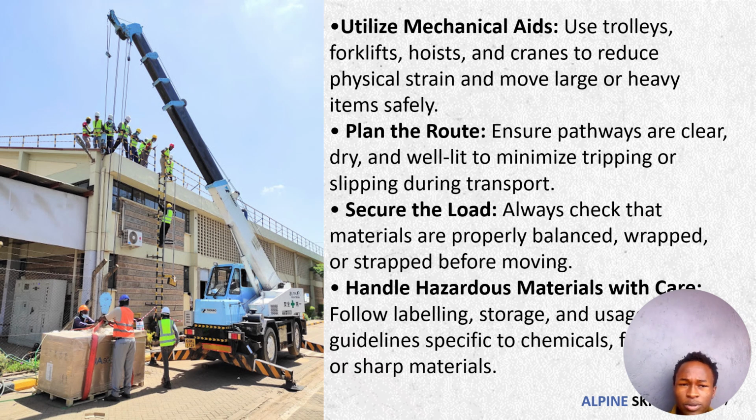You have to plan the route that you're going to walk around the construction site, and then you have to secure the loads. You have to make sure that the loads are adequately balanced, wrapped, and strapped before moving them. And then you have to label hazardous materials so that the construction workers can read and know how to properly handle such materials.